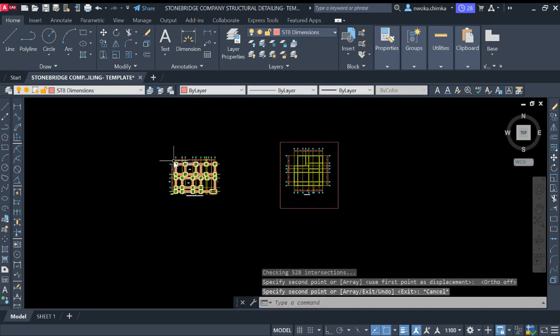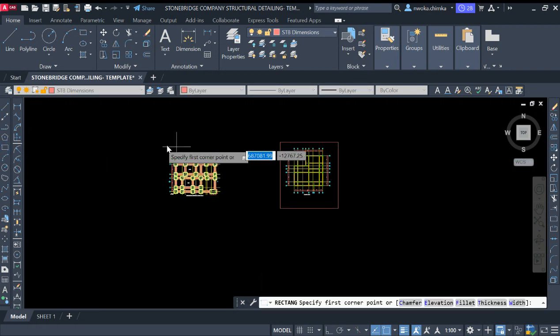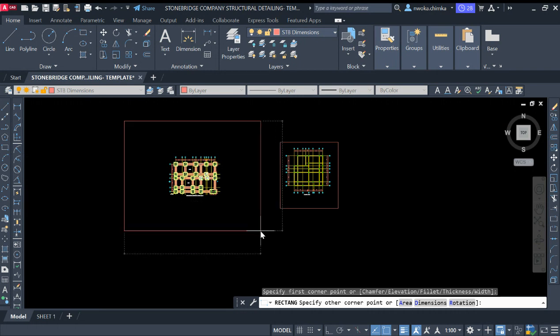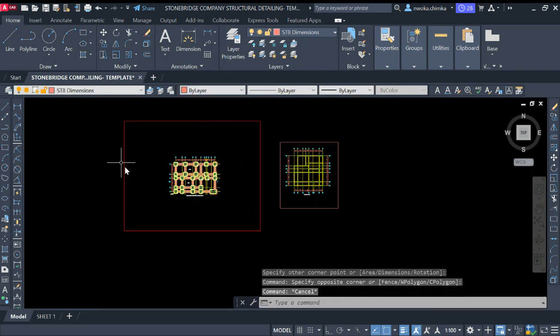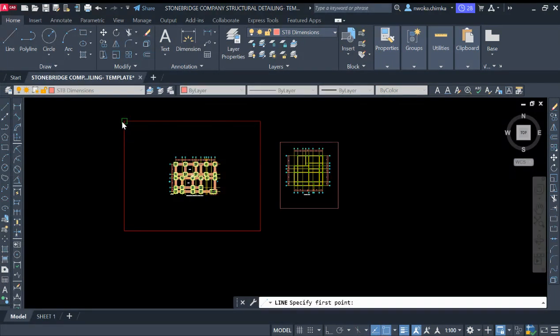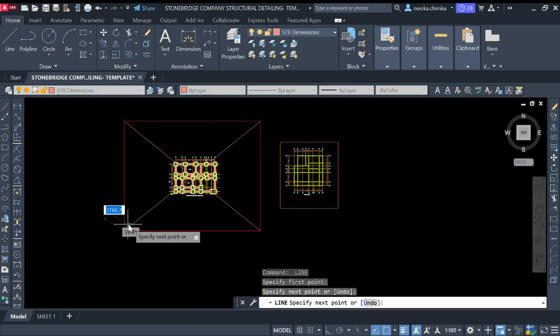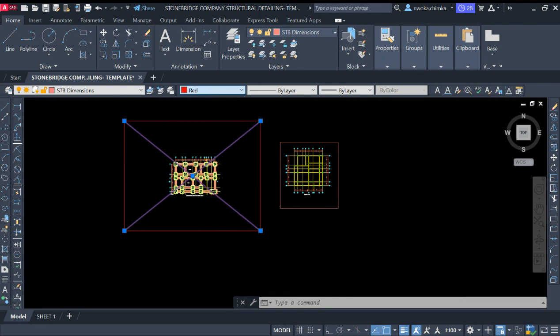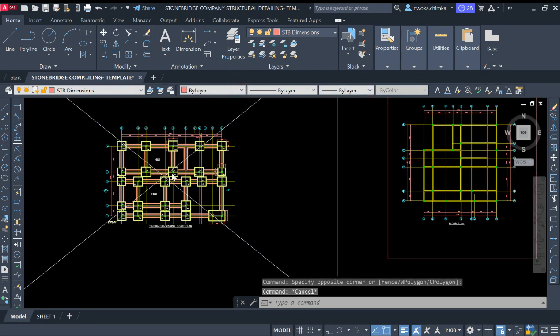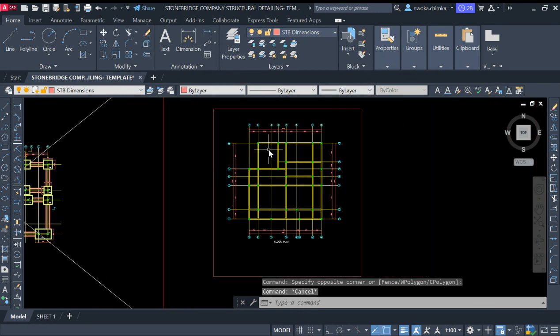Now, when you paste it, I always advise you to create a block around this place. Let me change this to red color. Create a block around this place and then cross it this way so that you don't mistake it for your current or proposed structural drawing which we are performing. So you just create something of this nature so that you will know that this one right here is just a go-by or a template which you are following to produce your own structural drawing.